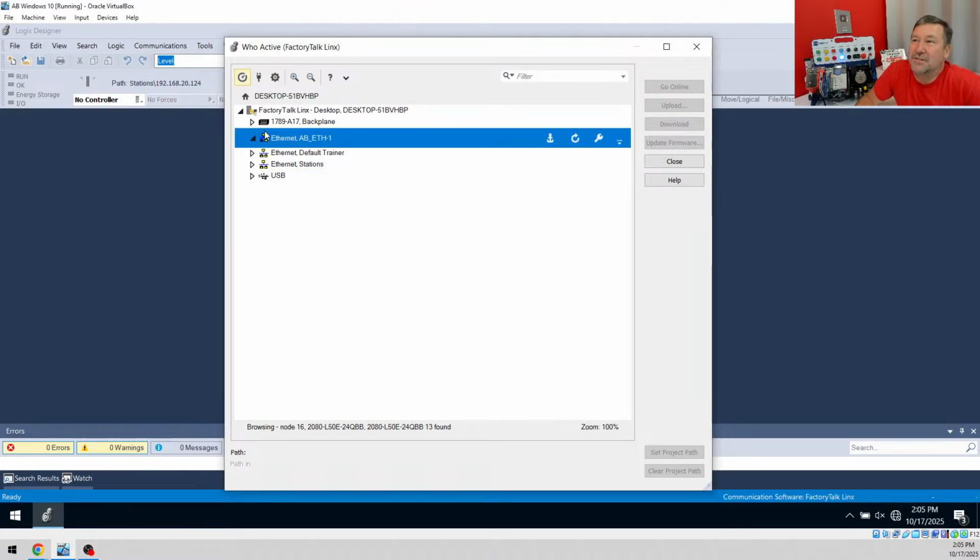So our boxes are marching right now, and we do not have anything showing up on our list. And here's what I always say. This is one of those points that we kind of pair off of, all right, which way do we need to go? If your boxes are marching and you're seeing a lot of devices in your list, then chances are your problem is that one device is not showing up. Now, if everything in your list disappears, then chances are the issue is in your computer's configuration.